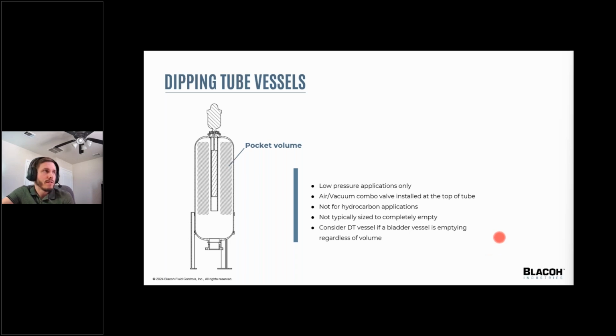As with any valves, they require maintenance, so just keep that in mind when selecting a vessel type. Your air vacuum valve will need to be part of your valve maintenance schedule. Whatever can go wrong with valves could make your vessel not function properly. Another concern here is vessel settling. If you're not anchoring this to a solid foundation, that can cause the valve to not seat properly.